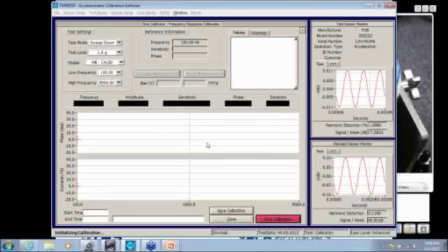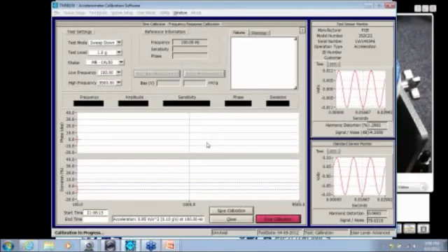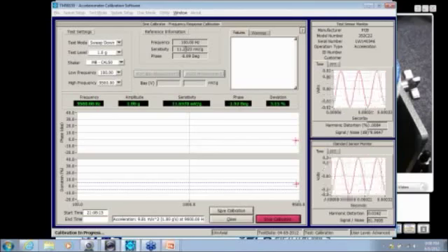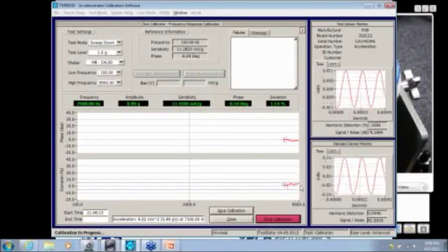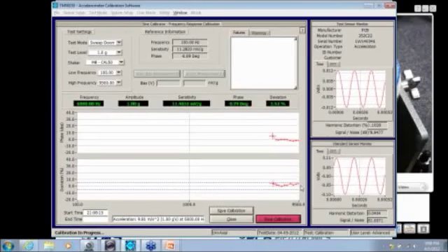I'll tell the system to run. So envision this being a calibration lab who is testing a sensor. They receive the sensor, they mount it on the shaker, and they start running the test. They're collecting data, and they look at the initial value. Okay, it's 11.23 millivolts per G. That's good. Frequency response at the high end looks good. Continue collecting our data.